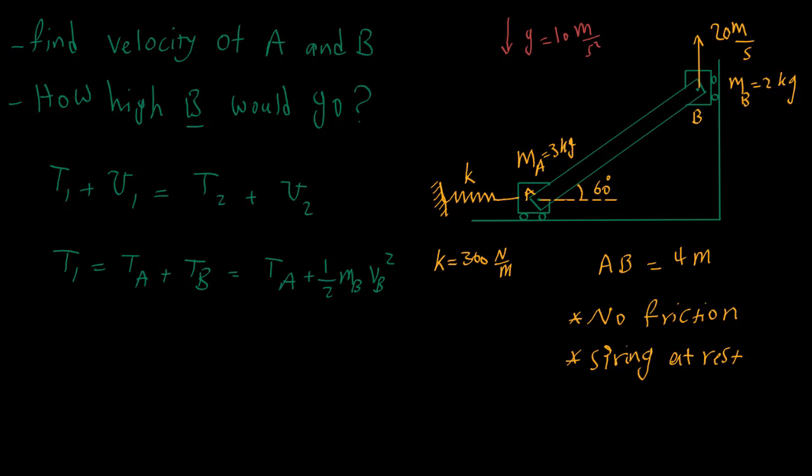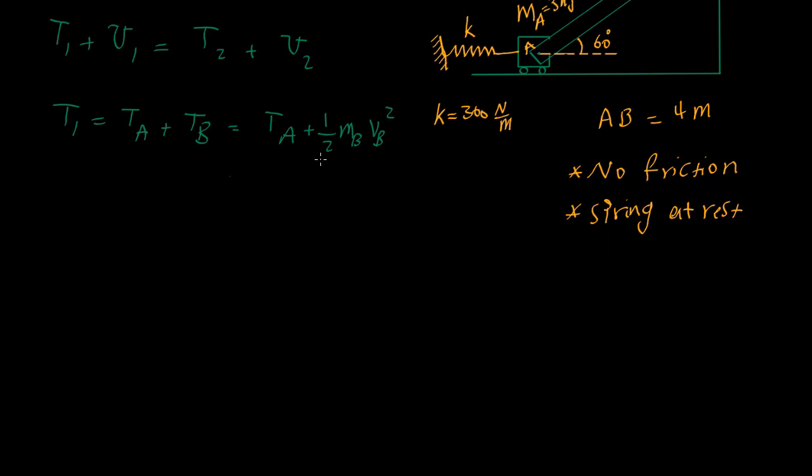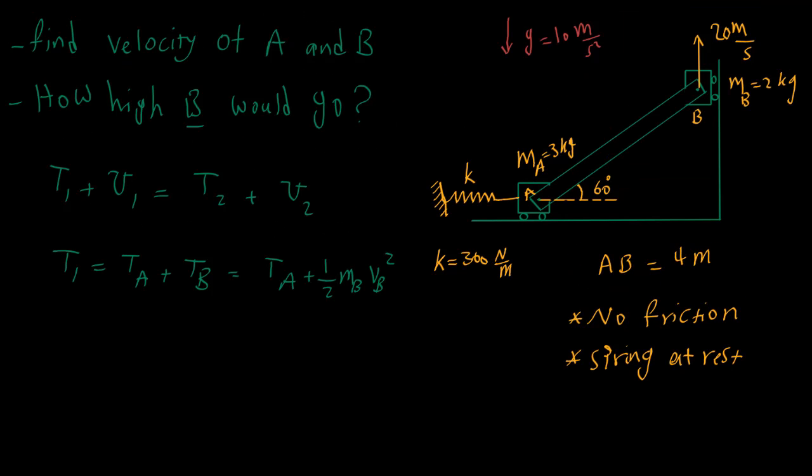So here the easiest way to calculate the velocity of point A, so there are actually two ways, basically the same thing, but two approaches to calculate the velocity of A. We can write down the velocity of point A based on point B. We would have omega, the angular velocity of this link, showing up in that equation, which is an unknown, and then force VA to be only in the horizontal direction.